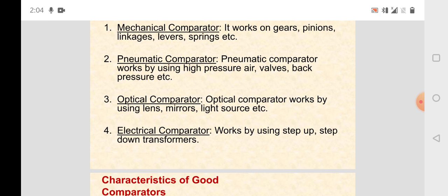So it can be a separate setup to be used for the comparator, like optical comparator. So these are certain disadvantages, and it cannot be used for mass production, or we can say continuously we cannot use optical comparators, as it requires the dark room and the setup and all these things. So all the time it is not possible to check the dimensions continuously.